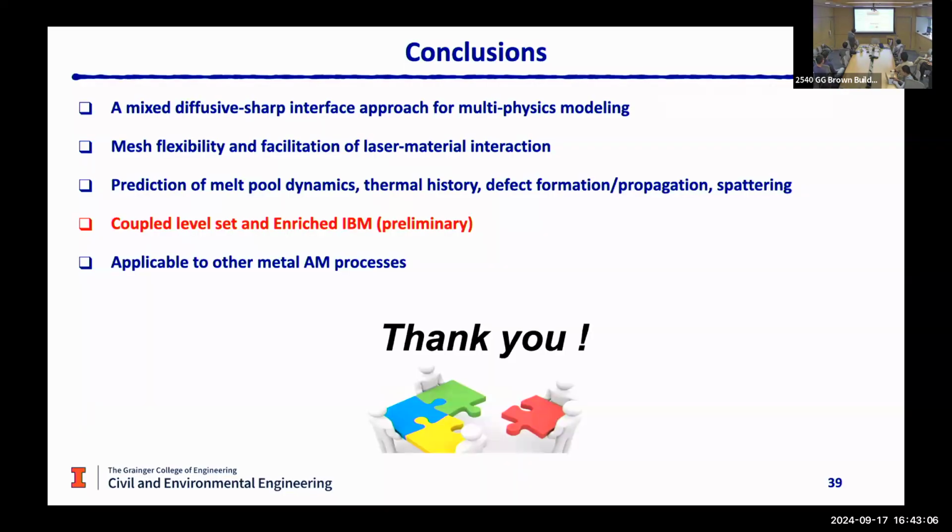So with this, let me summarize my presentation. As I mentioned, simulation and modeling of additive manufacturing is really challenging. To overcome some of the challenges, we first developed a mixed diffusive-sharp interface approach. Our technical goal is to maintain mesh flexibility, no mesh motion, no remeshing, and to have an explicit treatment for the laser material interaction.